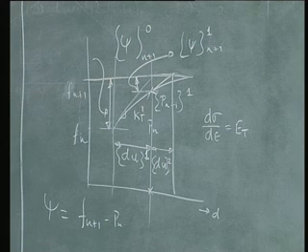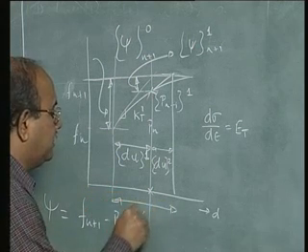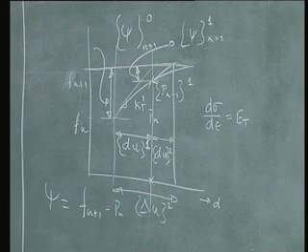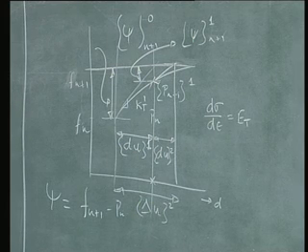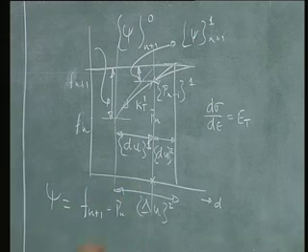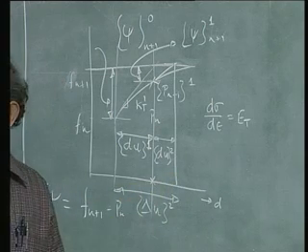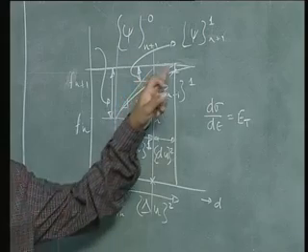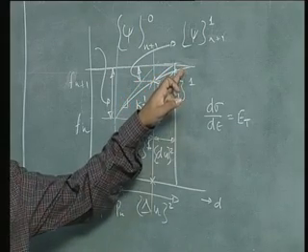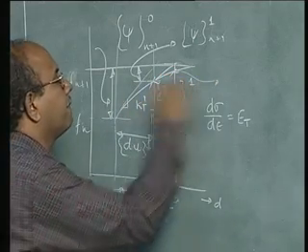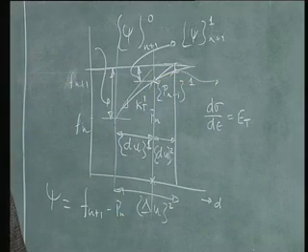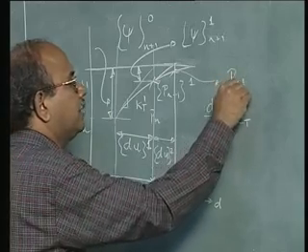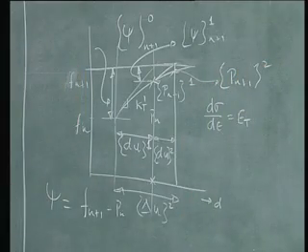So the sum of these two is delta u at the end of the second increment. Is that clear? Okay. So now at that point again I calculate what is sigma and then what are the internal forces. I hit the graph now at this point. Look, I have raised this P, moving closer. So again I am here. So that will be my internal forces at the end of the second iteration. Okay. So that will be called Pn plus 1, 2.